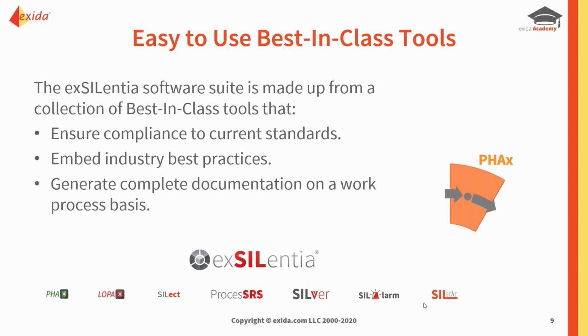Now under 1511, under the 2016 edition, we have to do what they call a periodic assessment of performance of the SIS and its SIFs. So that means that we need to be able to gather performance data.